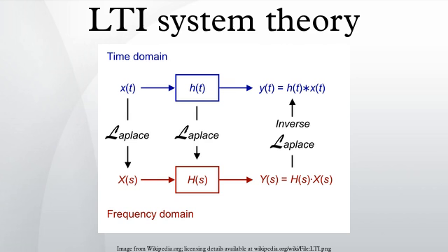The output of the system with impulse response h(t) is then the convolution, which, by the commutative property of convolution, is equivalent to the integral of h times the exponential, where the scalar H(s) is dependent only on the parameter s. So the system's response is a scaled version of the input. In particular, for any s, the system output is the product of the input and the constant H(s). Hence, e^(st) is an eigenfunction of an LTI system, and the corresponding eigenvalue is H(s).